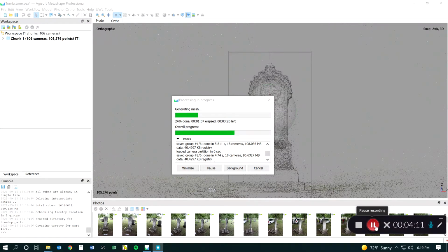As you can see, it drastically dropped from 7 minutes to only 2.5 minutes left to create our mesh. It all has to do with how well it's able to match up those depth maps and create the three-dimensional points, and then from those three-dimensional points create the individual triangles or polyfaces of our model. Since this is going relatively fast, we're going to let it keep running live, so you can see what's going on.